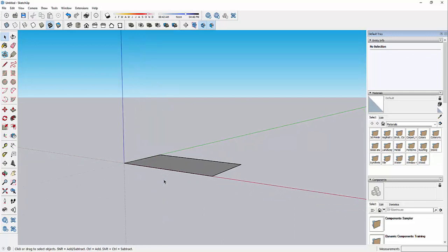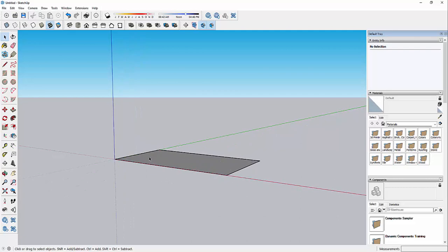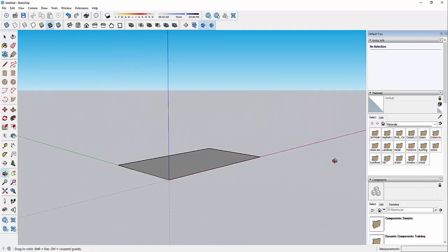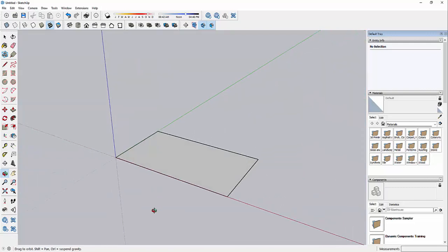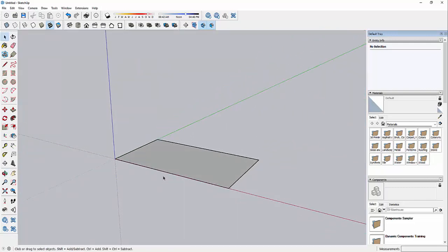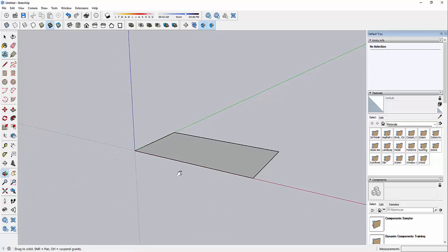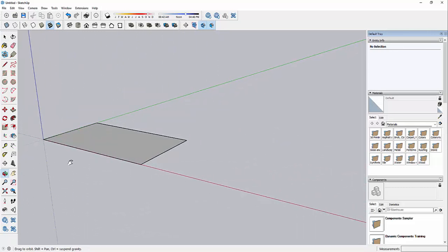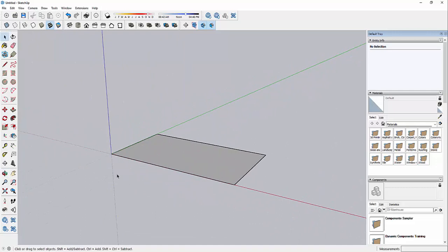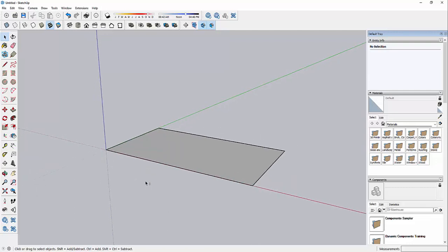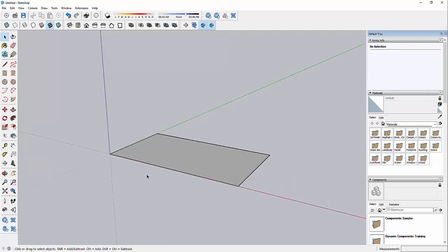that will zoom in. And a little bit about zooming, you can also rotate the view by holding down the middle mouse button, the wheel of your mouse like a button. If you hold down the shift key and hold down the middle mouse button, it will pan your view without changing the magnification. Okay, and then if you hold down shift and wheel up or down, it will zoom as well.